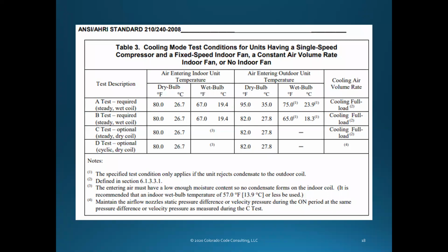Yeah, we've got these tables. We'll see. These tables go up to 115 degrees outside. And you suppose the capacity goes down? How is that outside thing working? Well, the refrigerant's going outside, and guess what it's trying to do? It's trying to get cooled off because it's carrying all the heat back outside. It's a heat rejection. Trying to get rid of the heat it just absorbed, trying to make your house cool.